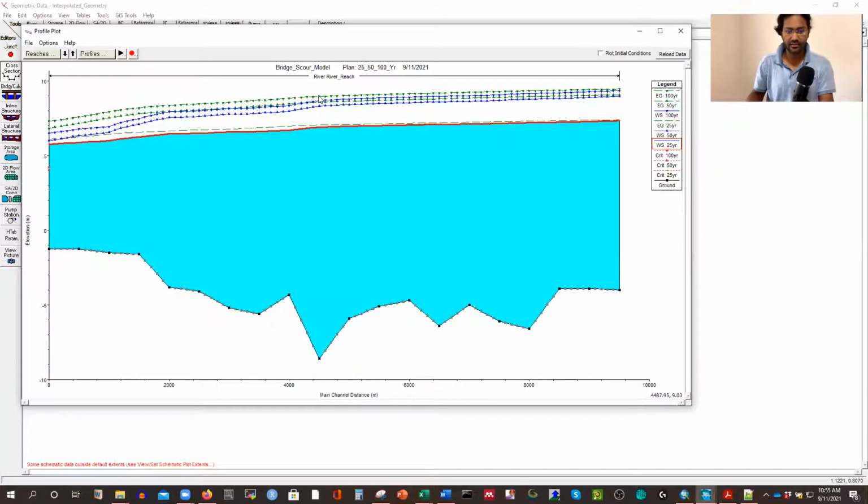Then your bridge level, the bottom chord of the bridge, will be here at least. So I'll show you how to design that level, and after calculating all this, we have to provide some factor of safety. And based on this information, if your water level is here, because the 100 year water level will be here, and if your bridge is here, then it won't pass any vehicle, any water vehicle, any ship won't be passing, right? Because it will touch the bottom of the bridge.